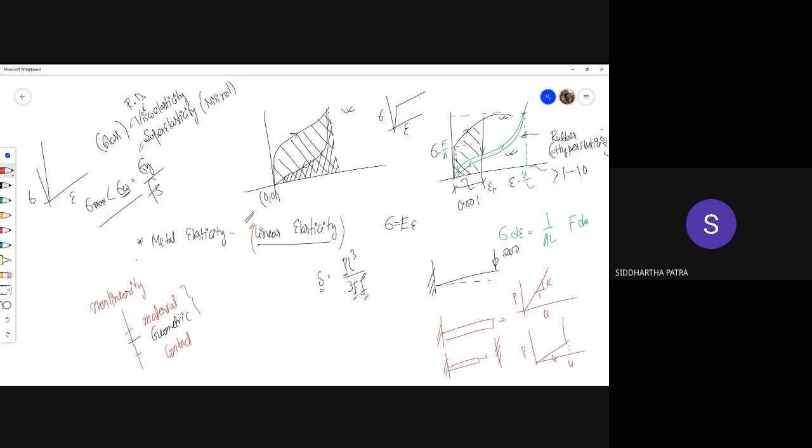And if you expect the stiffness to change from a finite value to an infinite value, or to decrease or to become zero, anything, that would be non-linearity. Now we are not considering any form of non-linearity. We are simply going for linear elasticity and geometric linearity and no contact.